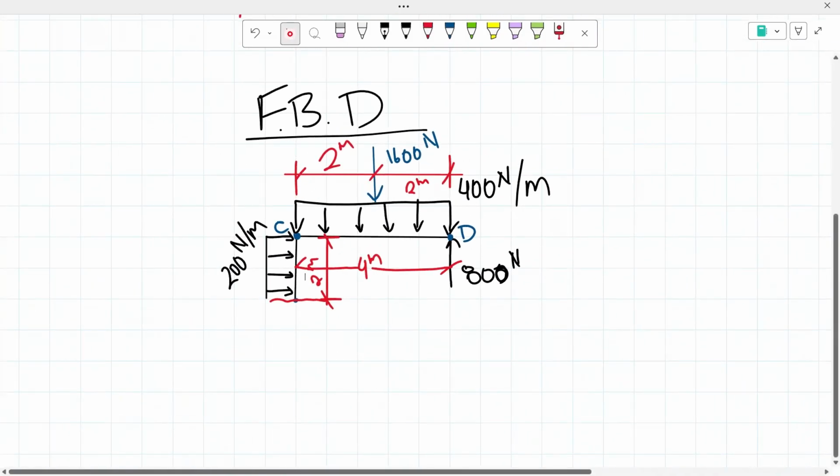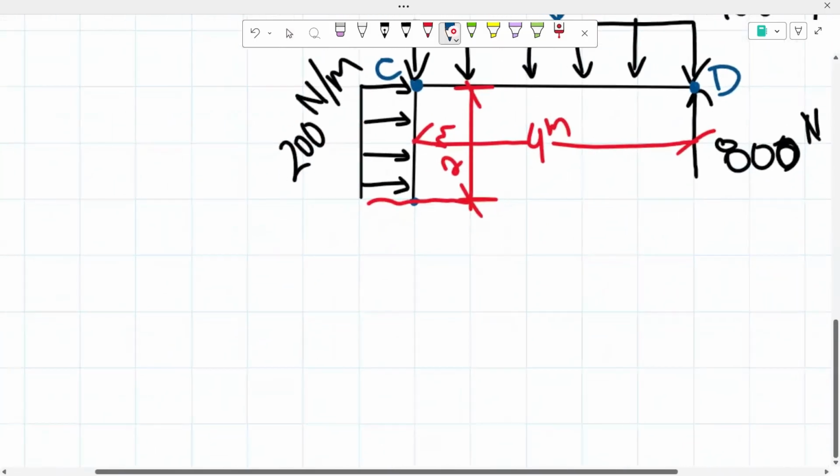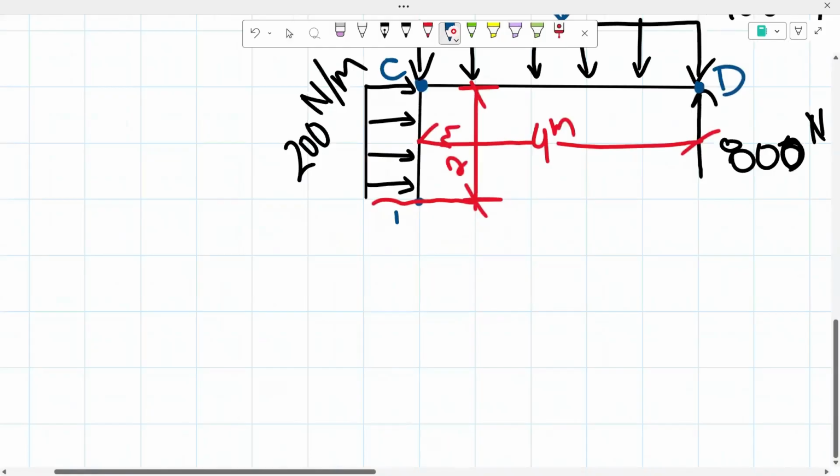From here, we're just going to be including our normal force, shear force, and bending moments based on our sign conventions. As you guys know, our cut in this example is to the left. Because it is to the left, we know to start off that our normal force will be going away from the cut. I'm going to write this as P or also as N.